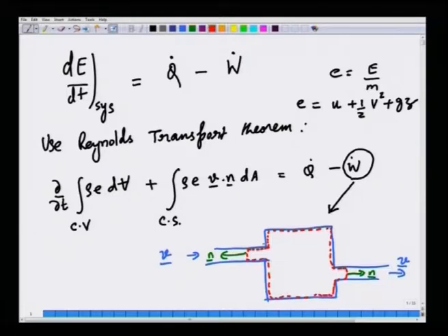So, in this control surface, suppose you consider the internal areas where there is flow, and where there is no flow because the fluid is stationary at the wall. That is called the no slip condition, which we will see in detail a little later. Although a stress acts on these internal surfaces, there is no work done on those surfaces because the surface itself is stationary. Here there is a pressure force that acts, a normal force, and fluid is also flowing. So, there is a work contribution at the inlet and outlet, which we later saw to be equal to the inlet and outlet terms.